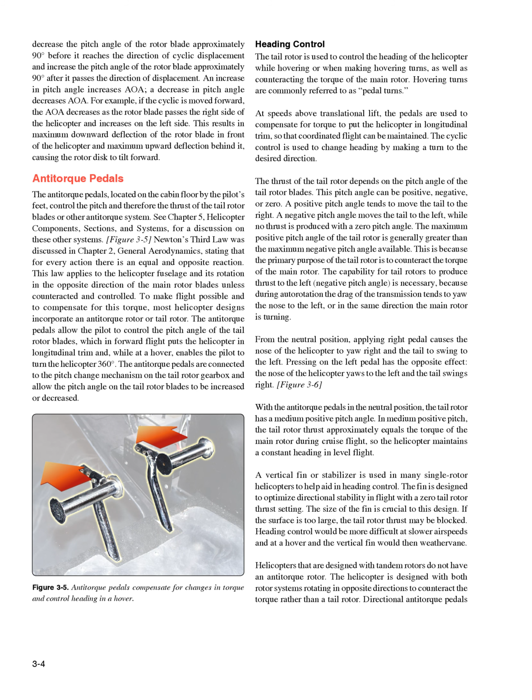Figure 3.6. With the anti-torque pedals in the neutral position, the tail rotor has a medium positive pitch angle. In medium positive pitch, the tail rotor thrust approximately equals the torque of the main rotor during cruise flight, so the helicopter maintains a constant heading and level flight.